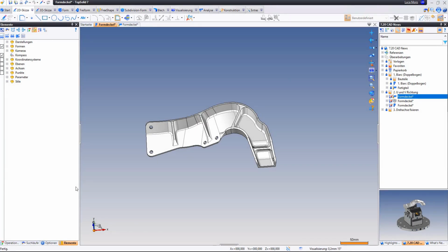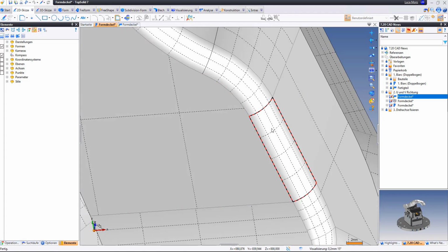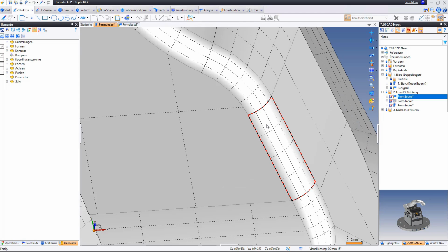The next new feature is particularly helpful if you work a lot with sweep machining because every surface has a U and a V direction. And if I go into the sweep machining itself, I can have these U and V directions for the surface displayed as well. But if I have multiple surfaces now, I'd have to check each surface individually. And I'd actually prefer to have it visualized directly. To do that, we can go into the visualization tolerance where this new field has been added called, in this case, number of middle surfaces. But what it does, if I set a value of 3 here, is it places 3 lines in the U direction and 3 lines in the V direction on each surface and sort of subdivides the surface. But it's just a visual thing.